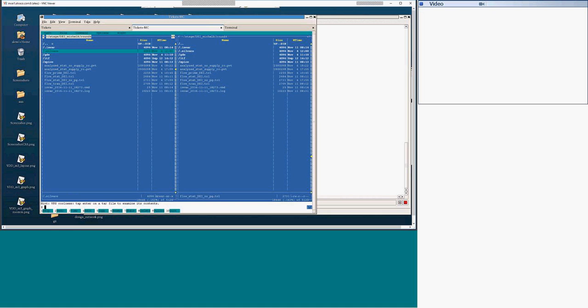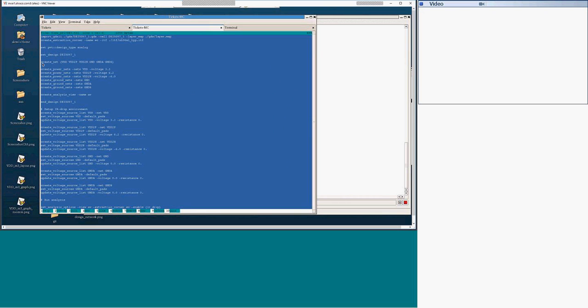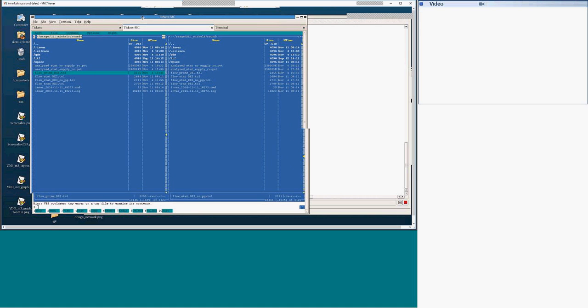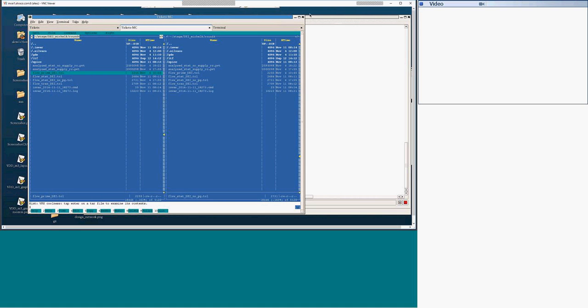Okay, so the difference is really minimal, and the major difference is that we include the command read SpiceNet list. Also in flow prime, this command create net. So you see we created 6 nets at once. When you run spice-based analysis, you do not need to do this because these nets are automatically recognized from voltage sources. So you do not need to create nets explicitly. Whatever nodes you have in SpiceNet list, the tool knows about their existence.